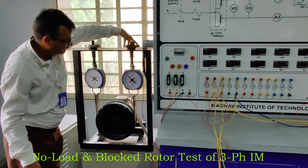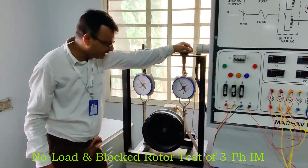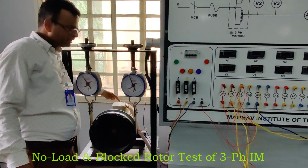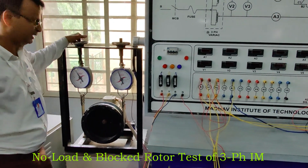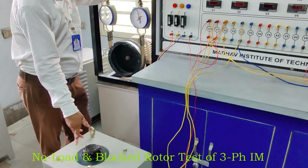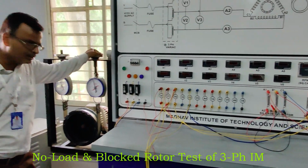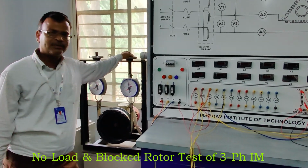Second thing, we have already learned in the theory part, this test is performed at the rated current. The rated current of this particular machine is 5 ampere, given on its nameplate rating. The machine rating is 5 HP, 5 ampere and 450. The rated current means with the help of the auto transformer, gradually increase the voltage up to 5 ampere current. The 5 ampere current is recorded from A1, A2 and A3. So these are the conditions for the block rotor test. No-load test at rated voltage and block rotor test at rated current.